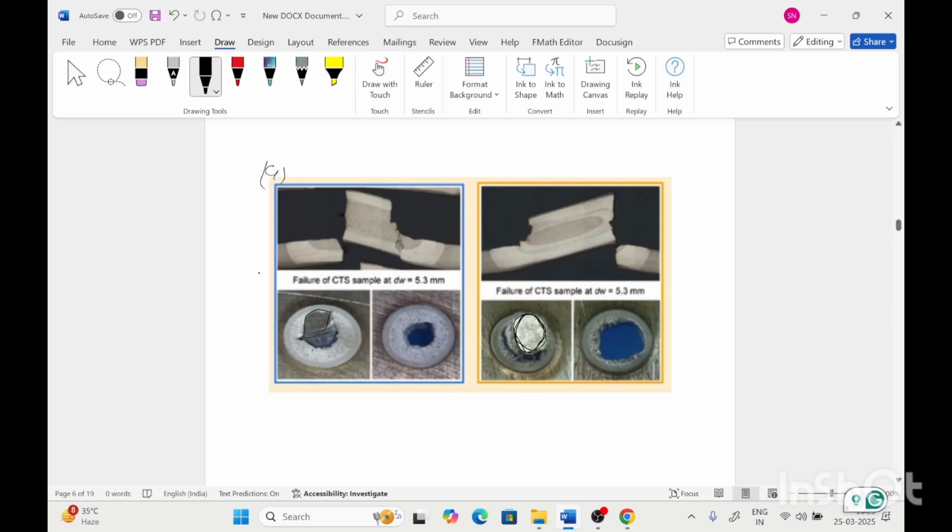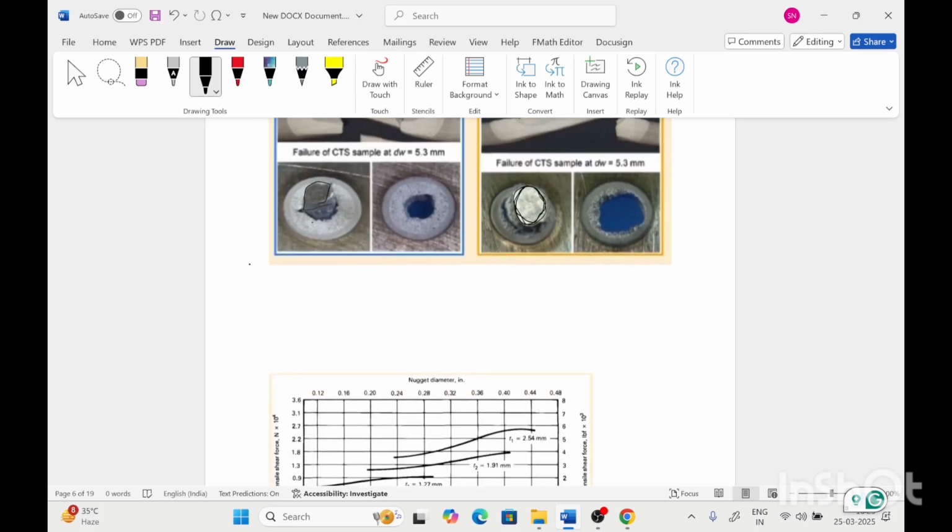The required plug ratio for a better resistance spot welding joint should be around 80%, or 0.8. The plug ratio can also be optimized by the curve of plug ratio versus current, time or weld diameter. By optimizing the current, welding time and weld diameter, we can obtain a 100% plug ratio, or 1.